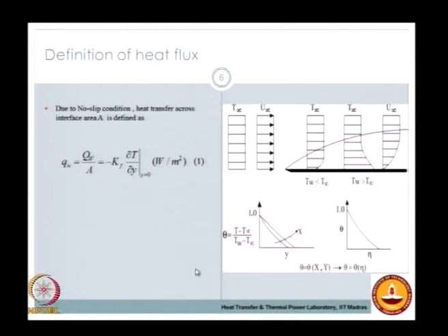And the good thing about this flat plate boundary layer problem is it's very interesting and more fundamental when you develop what we call similarity solutions. So if you define a non-dimensional temperature theta and plot that, you will find this non-dimensional temperature is a function of both the x coordinate, that is your axial distance along the plate, as well as the y coordinate or the height across the plate. Now if you plot these profiles, you find that it's dependent on both x and y.